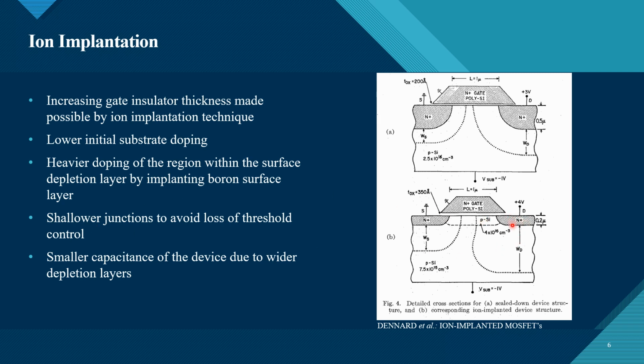And also reducing the dimension of the junctions, the shallower junctions, to avoid loss of threshold control. And such a design has another advantage as well. It has a smaller capacitance of the device due to wider depletion layers.